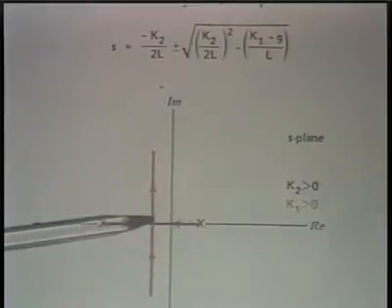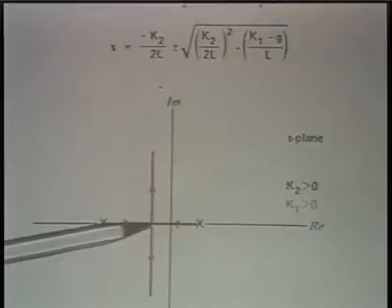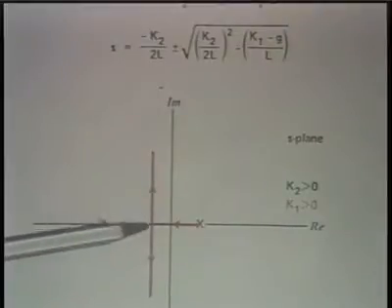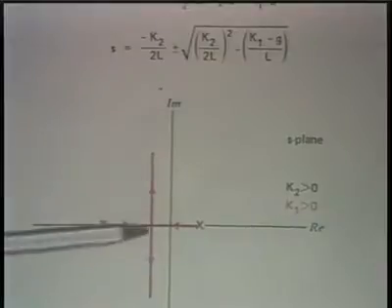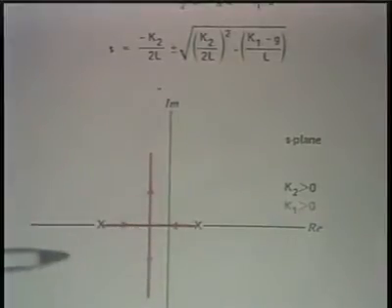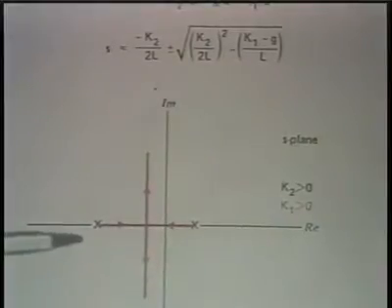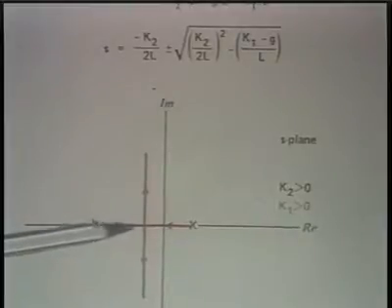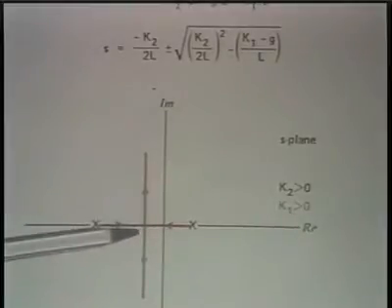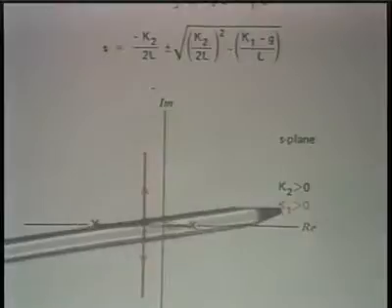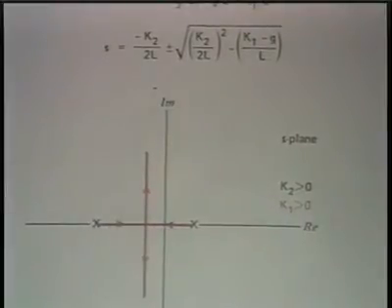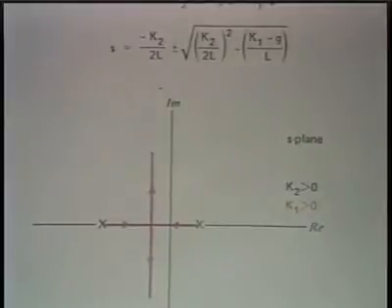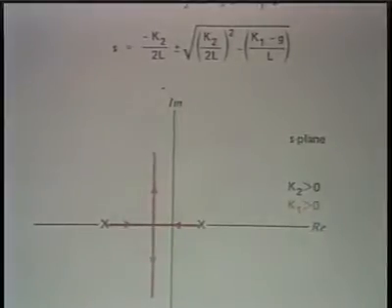The poles will move together, reach a point where we have a second order pole, and then those poles will split and move parallel to the j omega axis. So what's indicated here is the root locus. And what this represents, as long as we've made k1 large enough so that this pole moves into the left half plane, is a stable system.